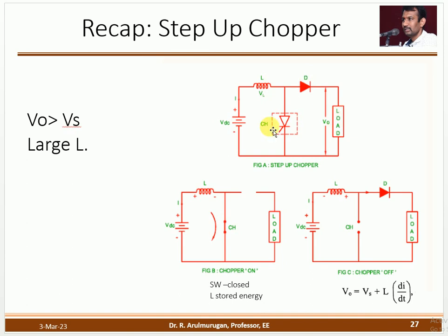How are the three components arranged? 3, 1, 2, rotated anti-clockwise. Who is the supplier? The supplier is the battery source. Who is the consumer? The load is the consumer. Here, the class B chopper is nothing but a boost converter, as you are saying.